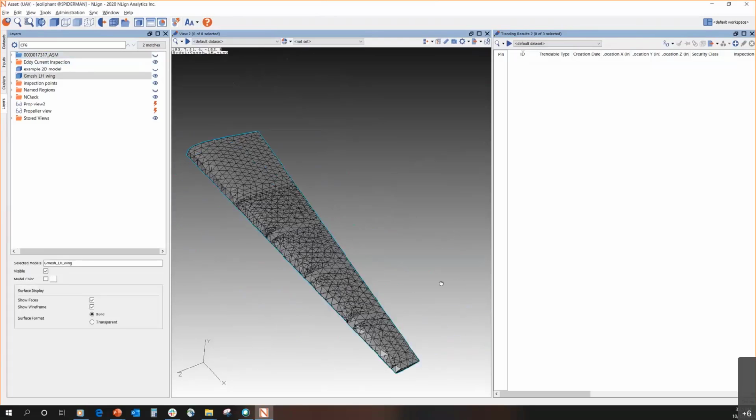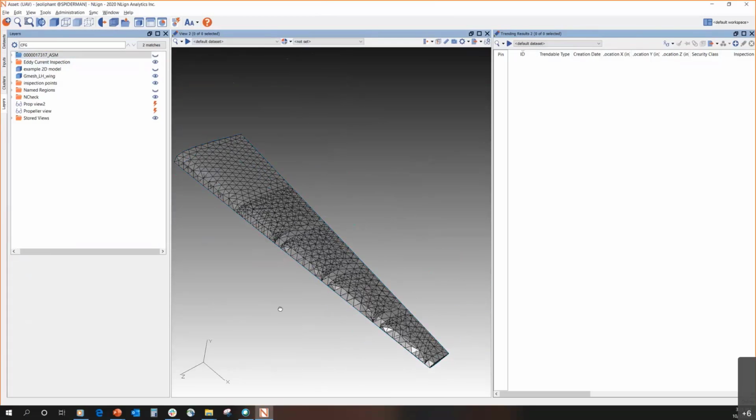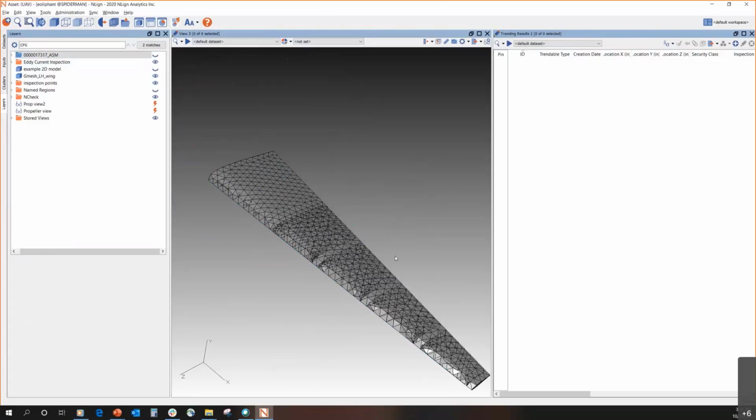One of the things that I did when I was working in manufacturing was I brought in some of the tooling for some of the different parts. So if your department works a lot with repairs and there's a tooling jig or some other fixture that you do a lot of repairs on, it may behoove you to bring in some of the model of that jig or that tooling, so you can see if there's any discrepancies that correlate to specific features on that jig or that tool.